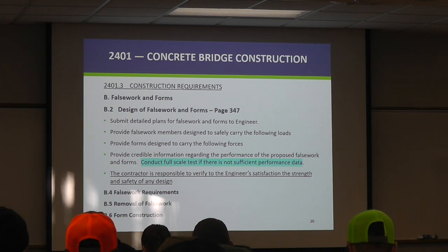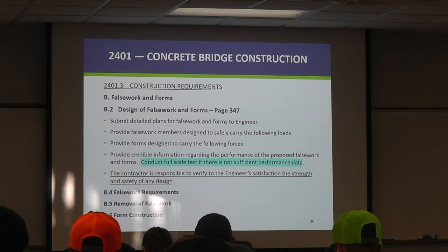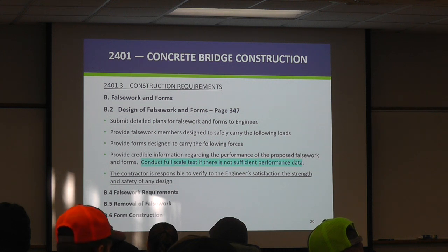And so we then want to design to carry that reinforcement. And also provide credible information regarding the performance of the proposed falsework. If there's not sufficient performance data, we need to do a full scale test.